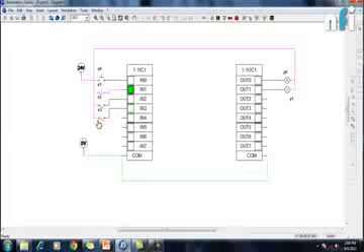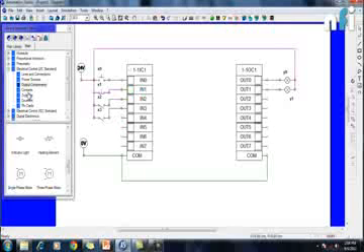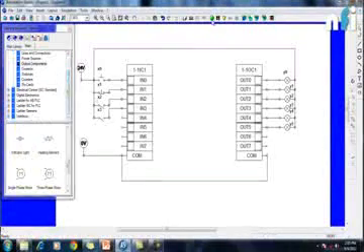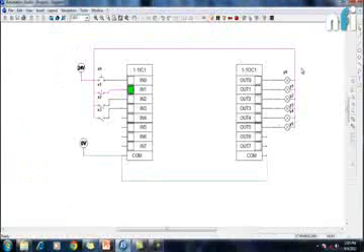So this is all about the wiring, how we have to wire the input section, how we have to wire the output section. We can similarly connect some more inputs. We can connect some more outputs like this. So you can see here now I have connected 6 outputs to the output section and a few inputs to the input section. Now in the next session we are going to see how to make a program, how to make these outputs glow by using the programming. We are going to see how to do the programming. It's based on simple logics: or, and, not, if, else, timers, counters.